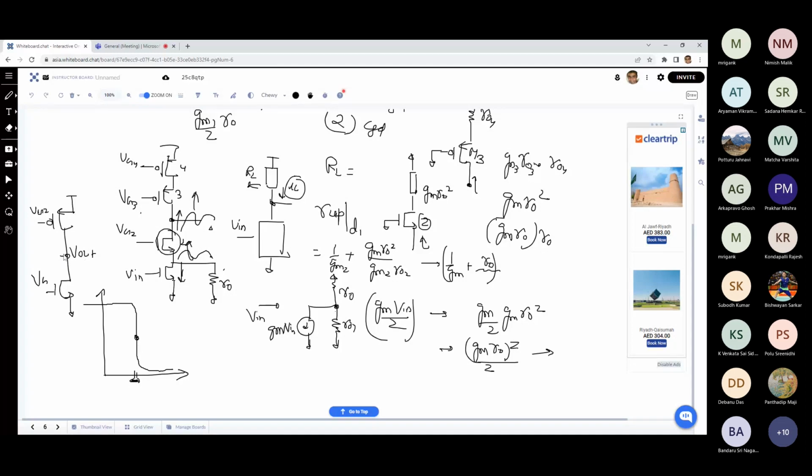Therefore, without feedback, we can't do it. So generally we use feedback for biasing this kind of circuit, and that is possible for differential mode. Single-ended it can be done, but it will require some capacitors, etc., which is again not feasible for the single-ended version.